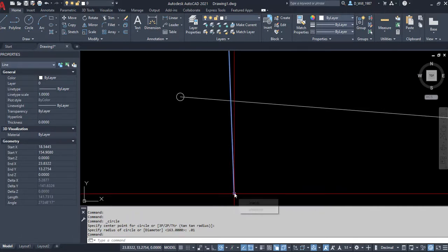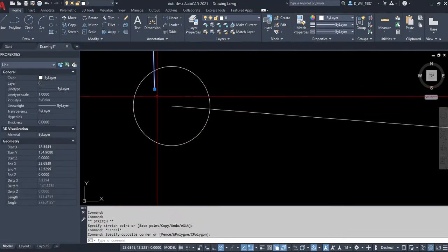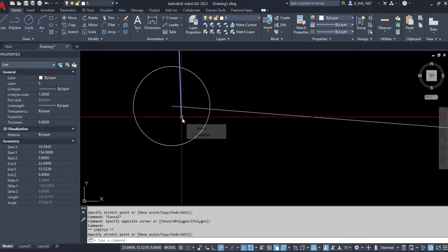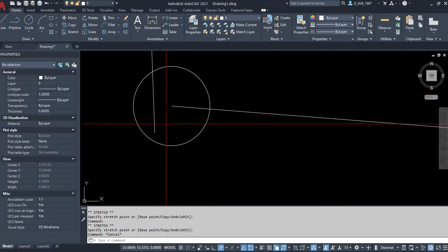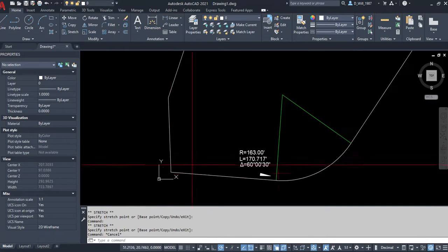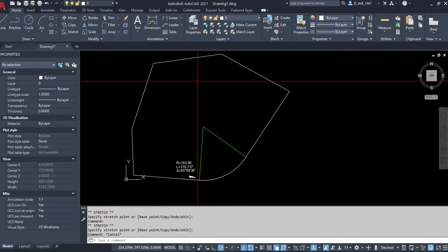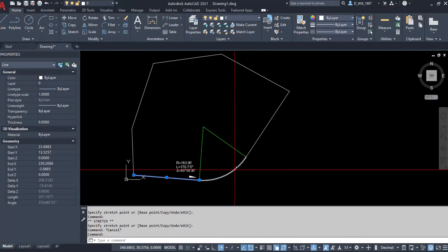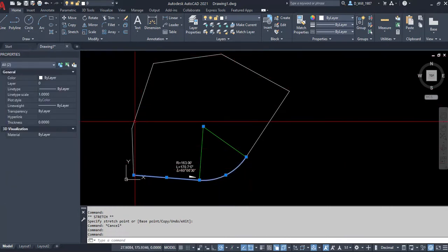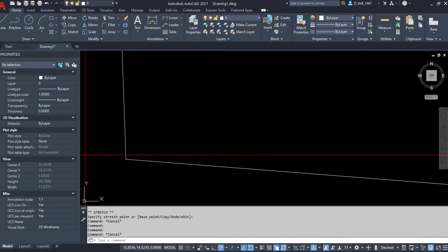This is way too far out, but if I was anywhere within the circle here, either here, or there, or there, even though it's not perfectly closed, it would be considered acceptable for working with parcel size pieces of property. Okay, so that's how I would lay your segments out. Start with the point of beginning, do your arc, do the rest of your line work, and check at the end to see how close you are and to see if you're within acceptable tolerance for a civil survey project like this.